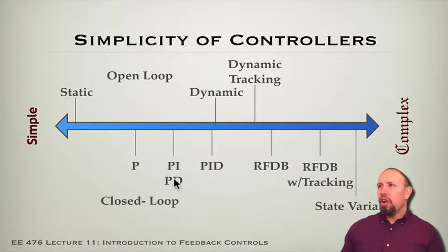So these are all of relative complexity. And then we'll talk about ripple-free deadbeat controllers. So that's the main thrust of our design approaches for this course, the ripple-free deadbeat. And so if you notice, the ripple-free deadbeat is a fairly complex controller by comparison, more complex than all these other controllers. And so if we're going to actually use this, we need to justify using it, that some of these other controllers will not suffice to do the job that we need to do.